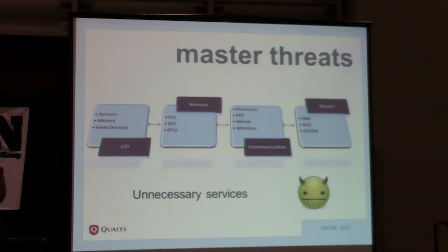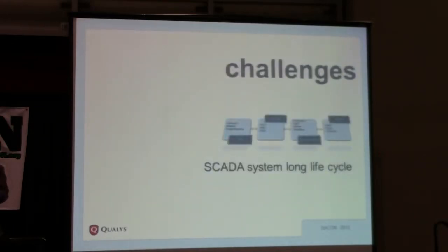Since, as I mentioned, these are off-the-shelf operating systems, your Windows, Linux, and I don't want to just beat up on Windows, I mean any off-the-shelf operating system, Solaris, there are a lot of unnecessary services running. So now you have to do a lot of security management on this system that you would do on a normal IT system. You have to make sure that this system doesn't have, for example, a mail server running just because it came by default like that. And off-the-shelf software, we talked about this already.